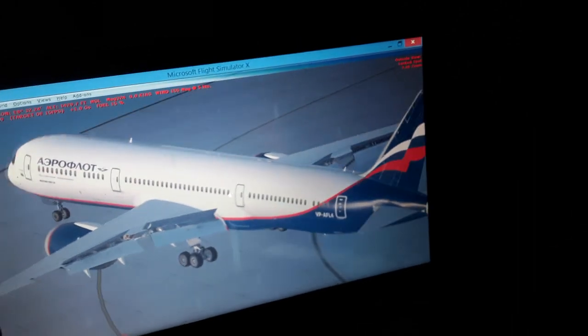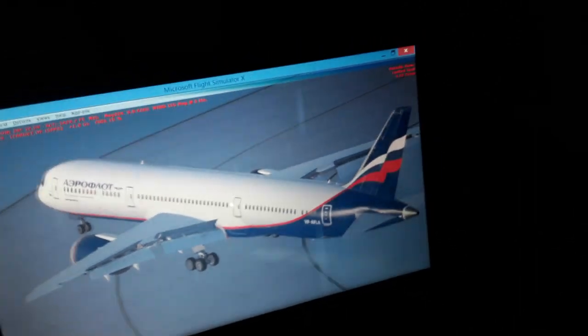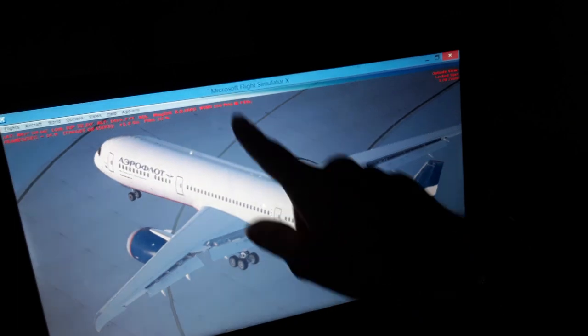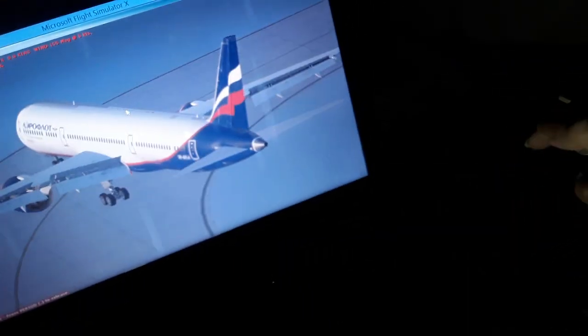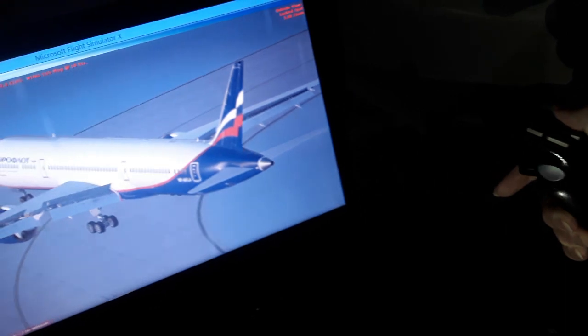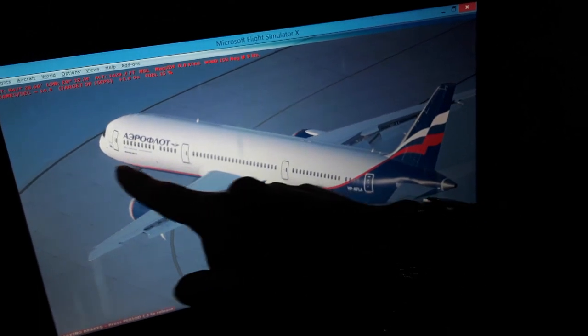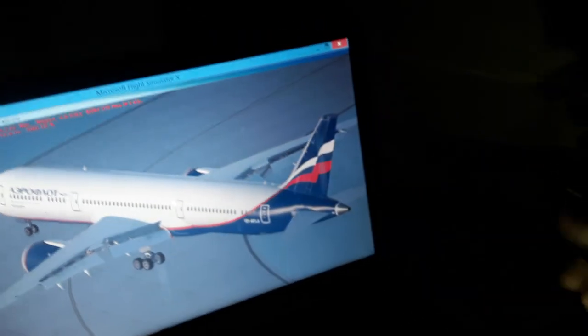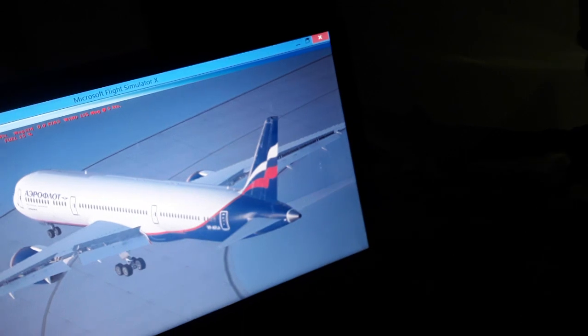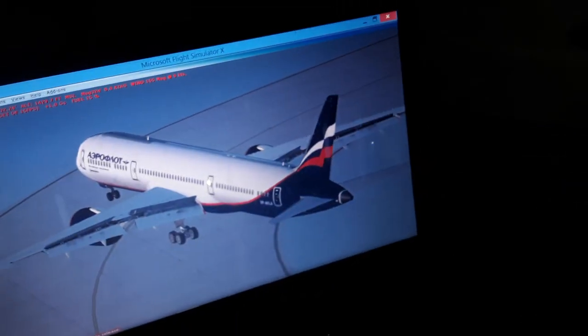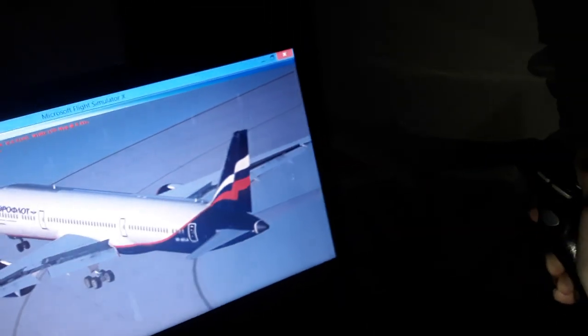So we have also where the mean aerodynamic chord is, the center of gravity over here. It's the yawing axis of the airplane. So the yawing axis is the rudder in an aircraft to make left and right turns using the rudder pedals. And also on the ground, when you take off or land, or you are taxiing, you can also use the nose wheel together with the rudder. In the rudder pedal system, it's automatic. You don't need to do a changeover.